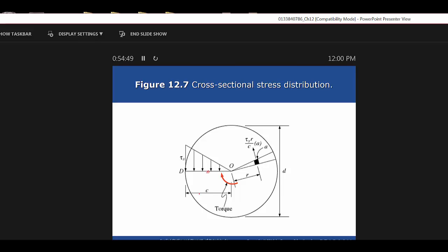So that last equation, to find the shear stress if you know those others, is 12.2. 12.3, if we want to find the max resisting torque, or the allowable torque, we'll take the allowable shear stress that would be given in the charts, times the polar moment of inertia divided by that radius value.